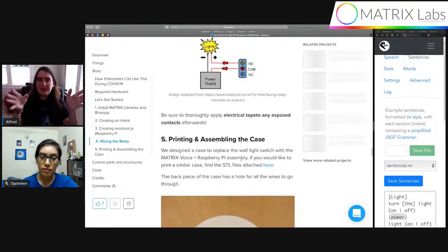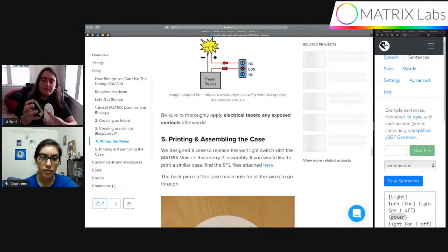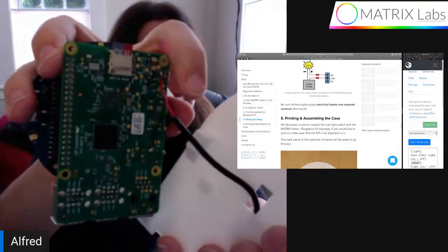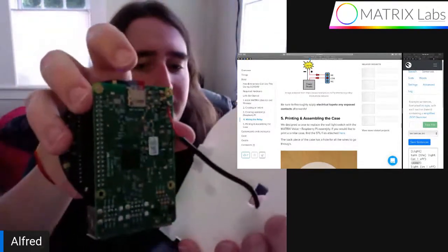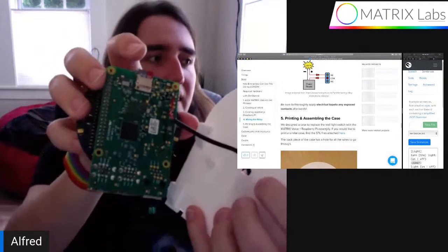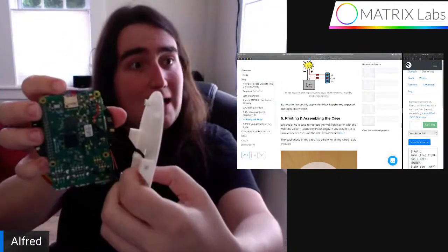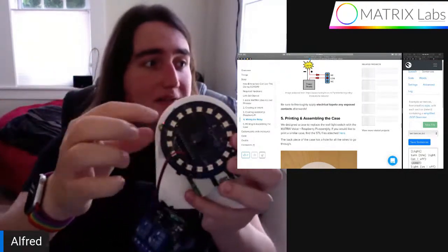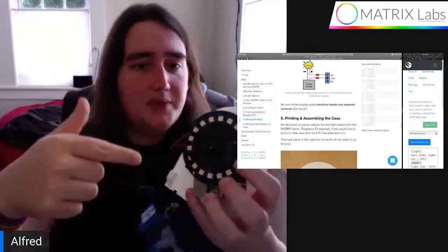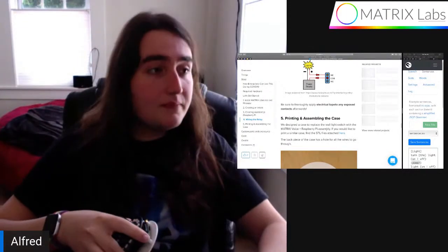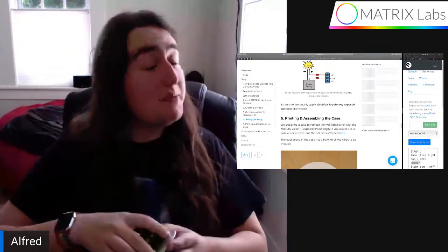And you know, safest method is, if you're wondering how to power the device, you can solder some wires to some pins here. You can look up. So this, you know, this will void your Raspberry Pi's warranty by doing this. So up to you if you want to do that. But that's one way of powering it from underneath, instead of having like a micro USB cable, which wouldn't actually fit inside the case. You're using a Pi 3, right? I am using a Pi 3, yes.